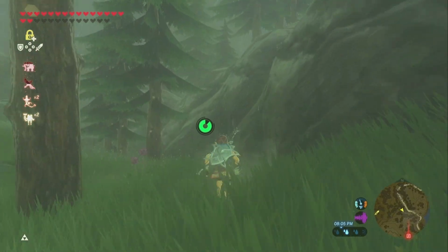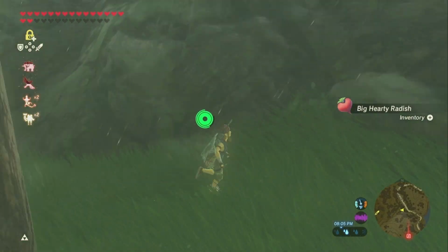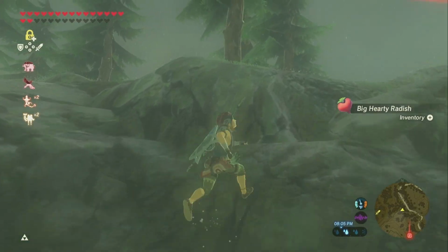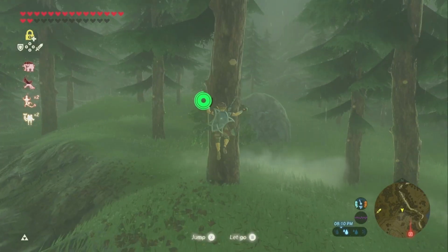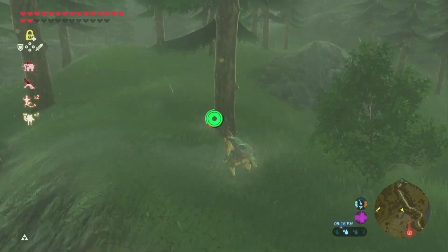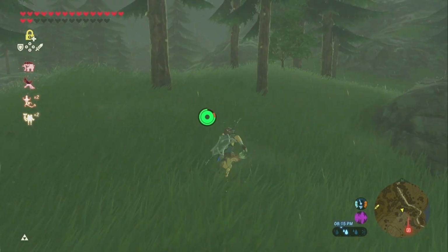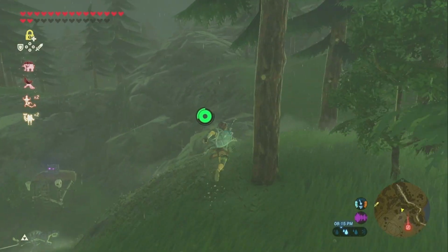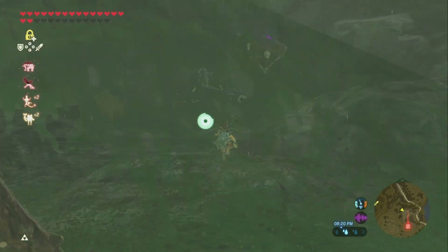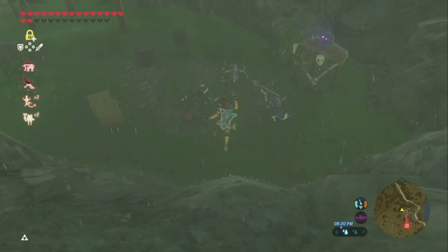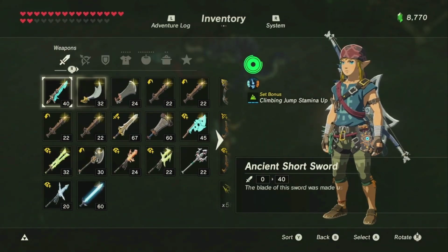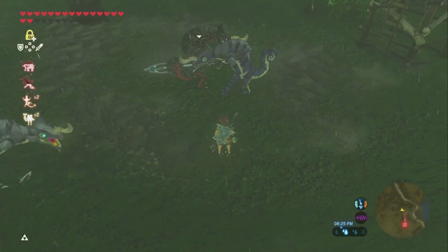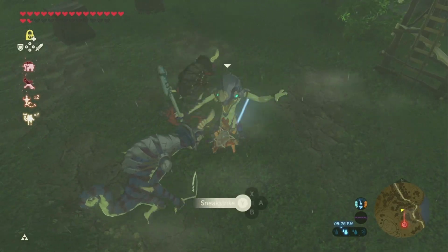The water heaters are installed in parallel rather than series so that each water heater does an equal amount of work. If the units were installed in series, the downstream water heater would be fed by the upstream tank, so it would rarely kick on. The first water heater would do all the work most of the time.